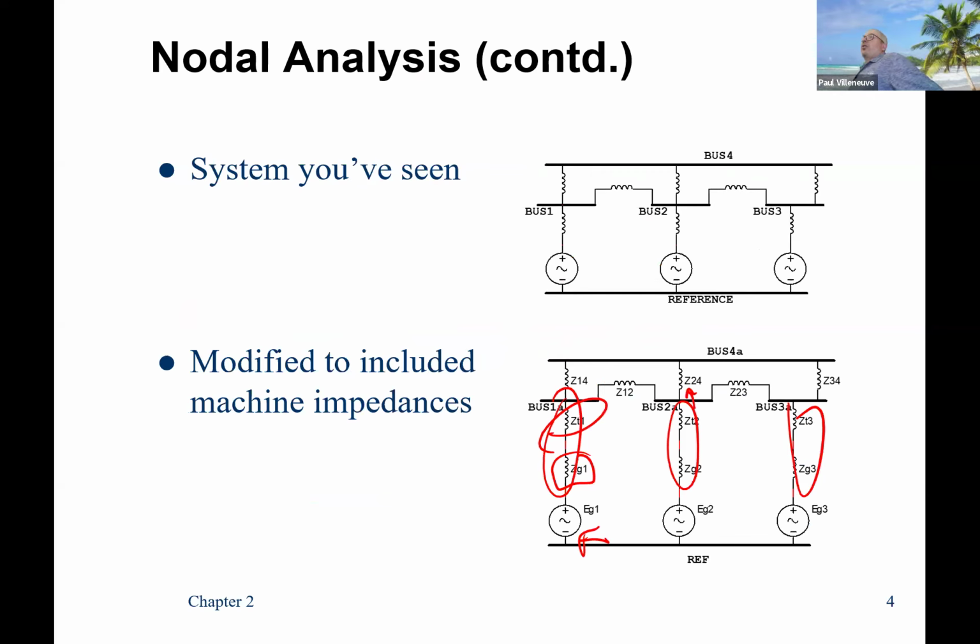And when you do short circuit analysis, most of the time, although that's changing a little bit, you might do either a flat start, assume every voltage is at like 1.03, sorry, 103%. You'll understand where the 1.03 comes from. Or you could do this current injection approach, which calculates some voltages at buses throughout the system if you want to be a little more accurate in terms of your fault current calculations.